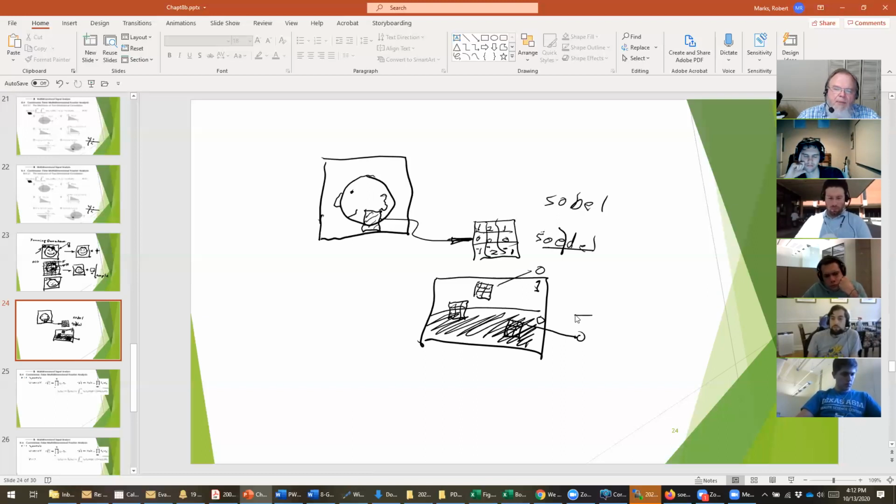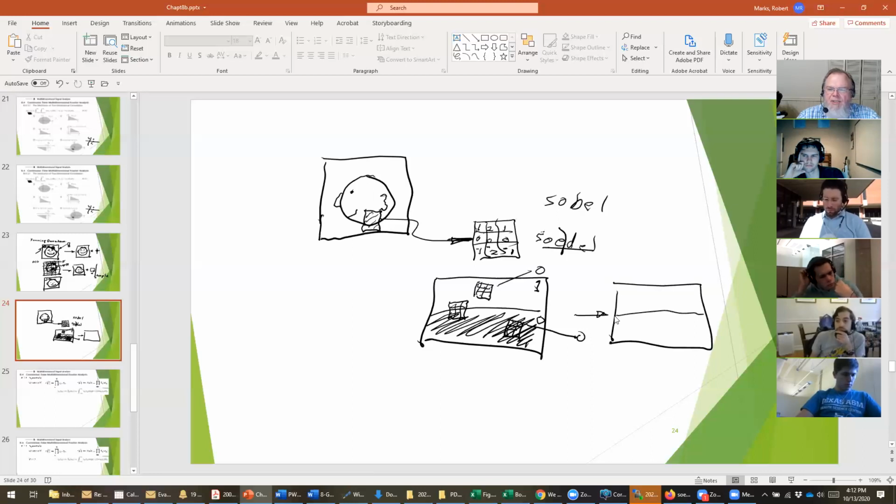And so what will happen then is once you apply this Sobel operator, what you will get out ideally is just the edge, the difference between the two values. So it's an edge detector. So you can see this is truly correlation, but it's kind of a convolution, right? Because we're doing the shifting all around, and we're multiplying everywhere by this result, and we get an edge detector.